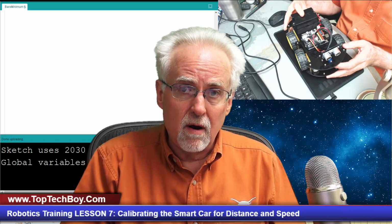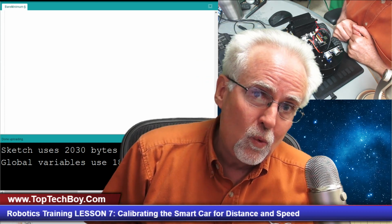Let's talk about what we are going to learn today. If I remember correctly, last week we showed how you could control the speed of the Elegoo Smart Car by doing an analog write to those enable A and enable B channels. If we do an analog write instead of a digital write high, we can control the speed. That is the good news. What is the bad news? When we did that, we broke our functions.